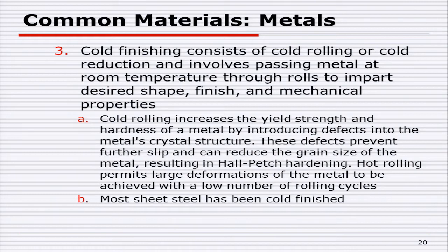It generates a tremendous amount of heat, by the way, in the equipment that's around it. But they'll do that multiple times to get wire from one size down to another size. And it'll go from a yield strength of around 30,000 pounds per square inch up to like 150,000 pounds per square inch. You can really get some high yield strengths by continually cold working these metals.